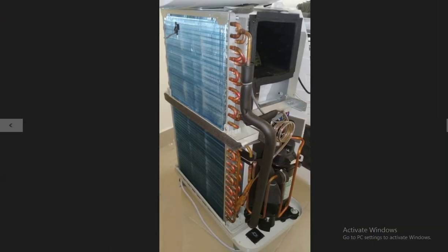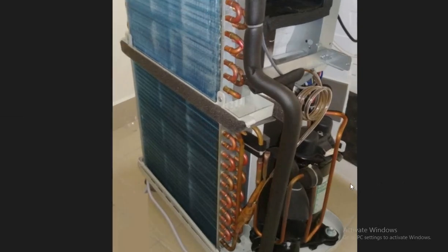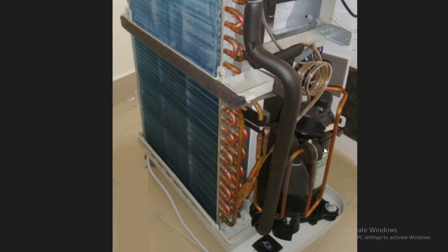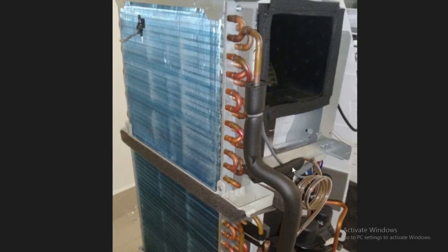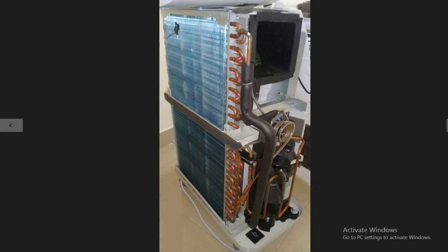See, there is one more example which I have taken. This was of a portable AC. So in terms of construction, here is the evaporator. Here is the condenser. You can find the compressor over here. Okay. So the high pressure refrigerant will pass through this tube and go inside here, and then after condensation the tube will take the rest of the refrigerant inside this capillary tube. It will pass into here where evaporation will happen, and from the top it will go back again into the compressor.